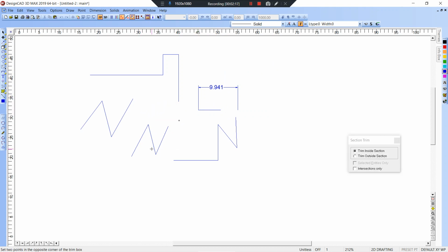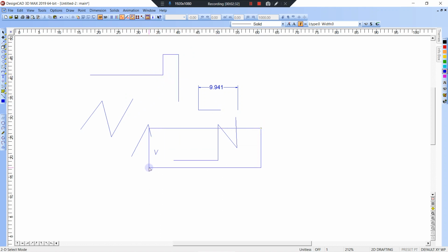So D will chop out what it's going around, and if you want to connect anything that it's connected to, see this is a polyline, if you hit Control, it'll select everything. So Control selects everything that it's touching, sort of like the left hand select on AutoCAD.